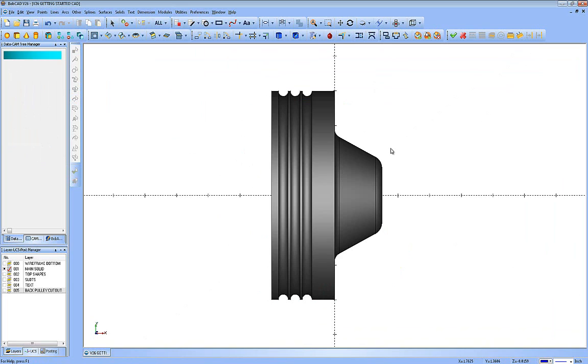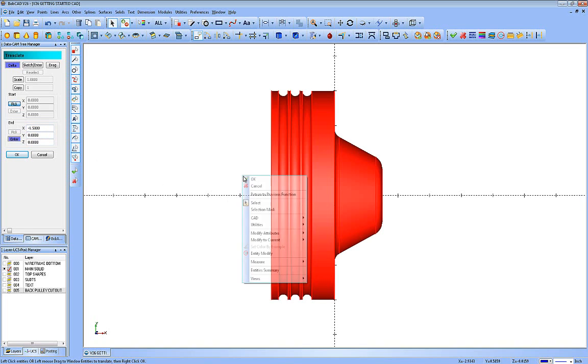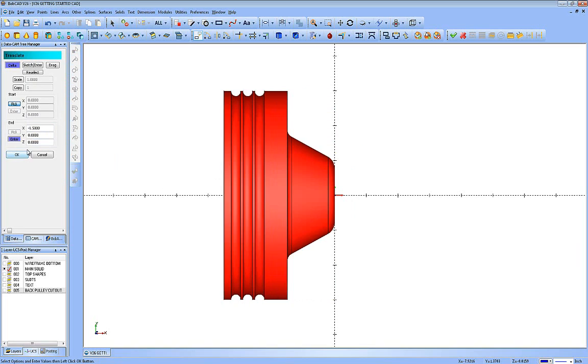You also want to orientate the part to grid 0 as it would be the lathe machine 0, because on the lathe portion of the software, the grid 0 is your machine part 0 for X, Y, and Z 0. So we're going to shift this over the height of this boss, which is 1.5 inches. We're going to use Utilities and Translate. We're going to go over minus 1.5, pick the part and OK it, and shift it over.